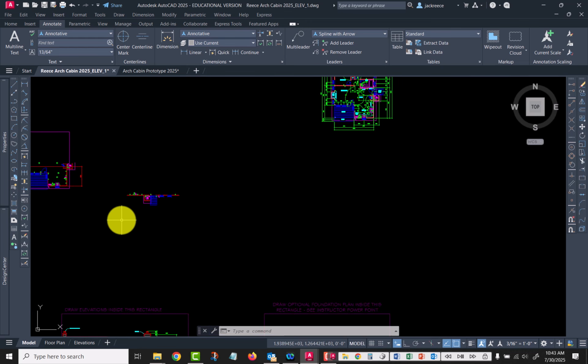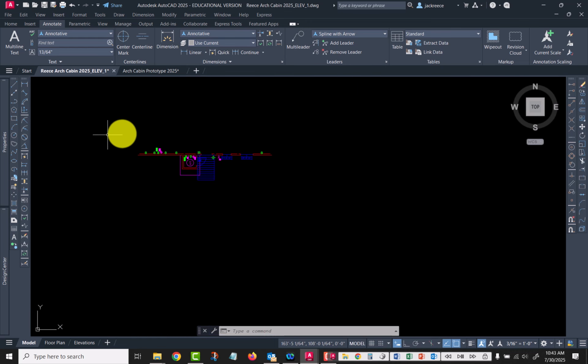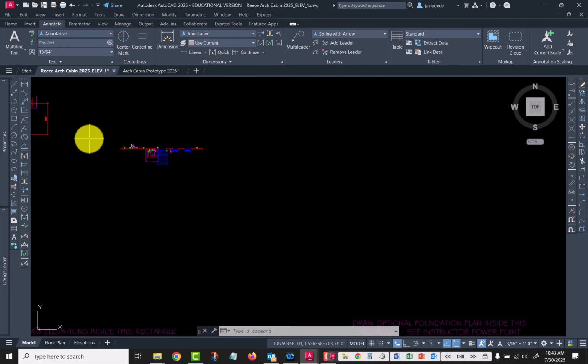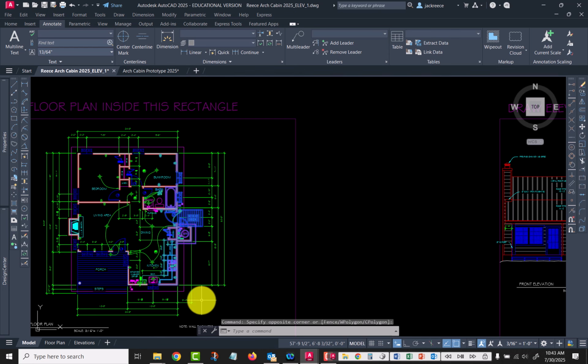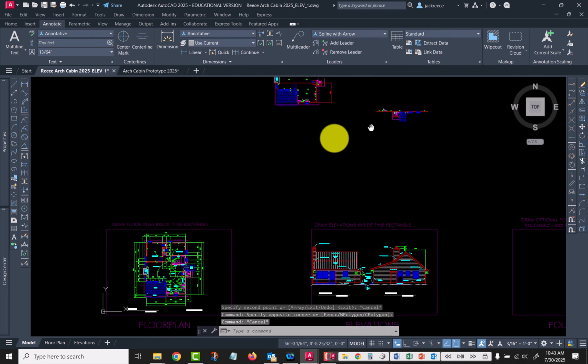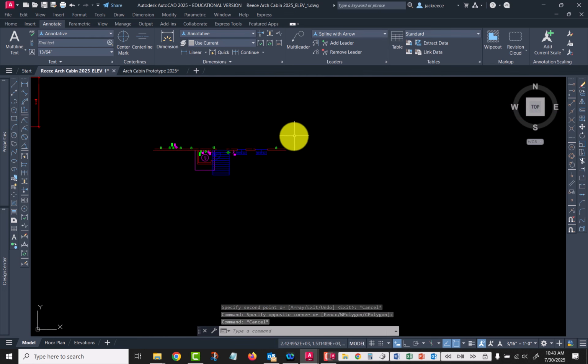And so what I did here is I copied the right side wall, I basically just came down through here and copied all of those things, brought them up, rotated them 90 degrees, and this is what I used to project down using construction lines on the construction layer to get the length of my walls, the center of my windows, you know, my door location, things like that.